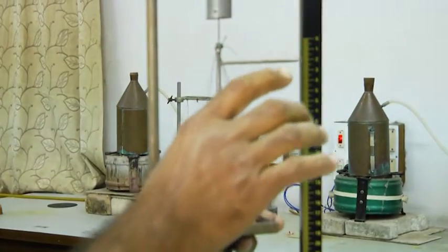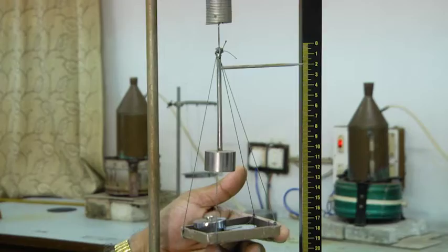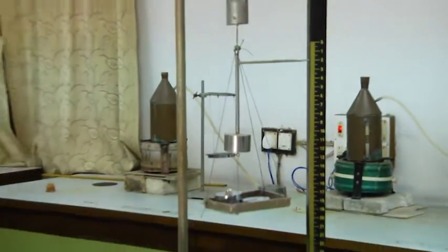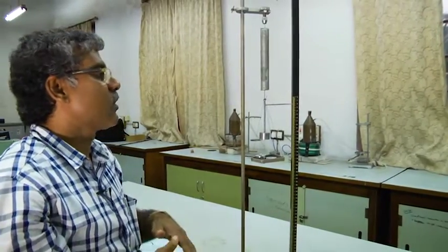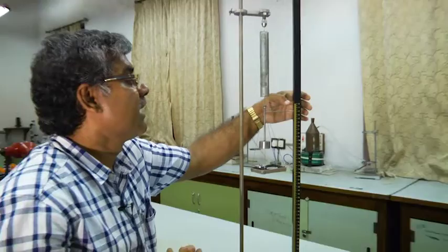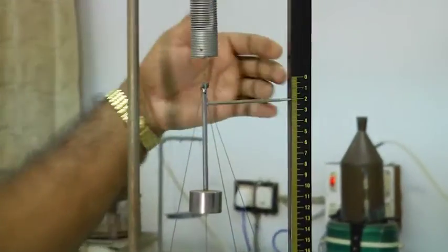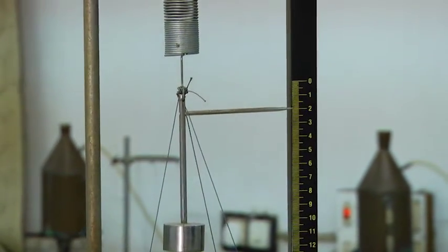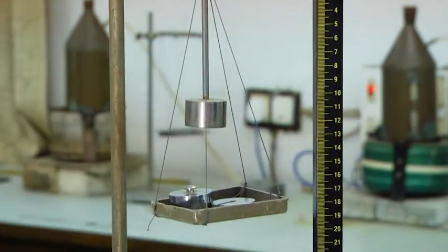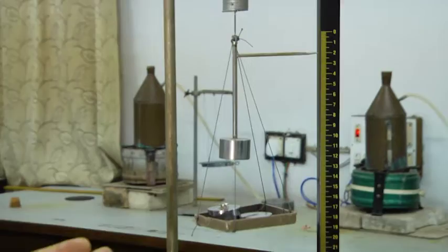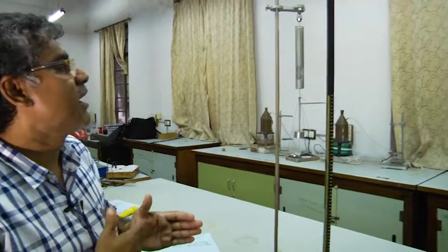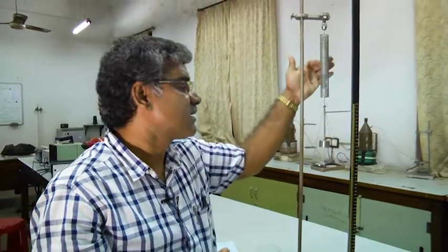So, then I will get 2 sets of readings, one when we are increasing the mass, another when we are decreasing the mass. Then from whatever the initial value was, it was basically 0. If it is not 0 also it is fine. Just subtract the initial reading from each reading, then you will get for each mass the extension or elongation of the spring.